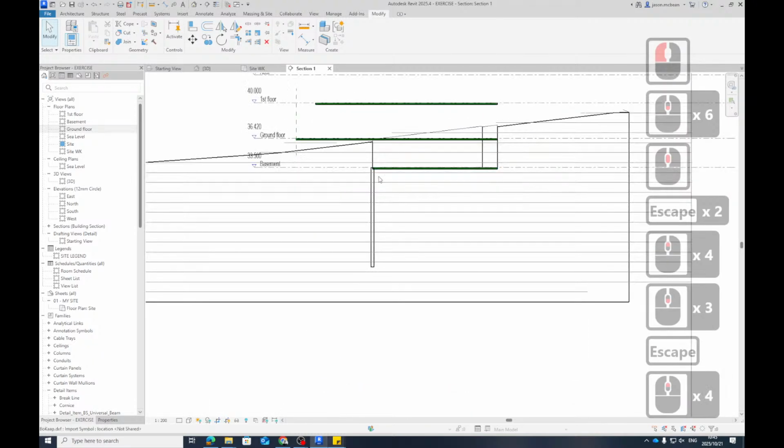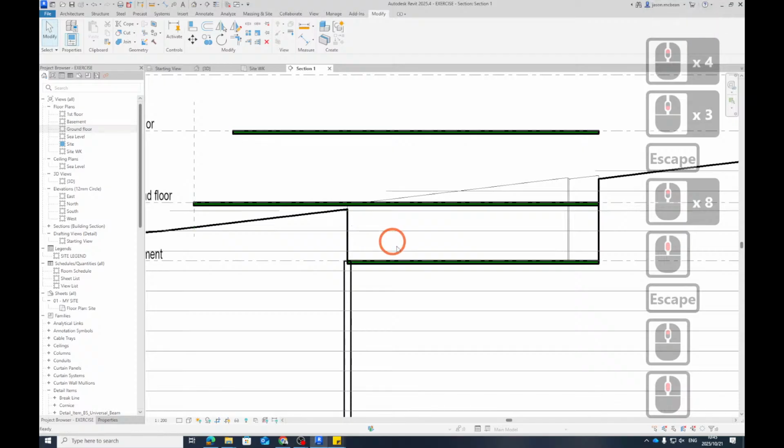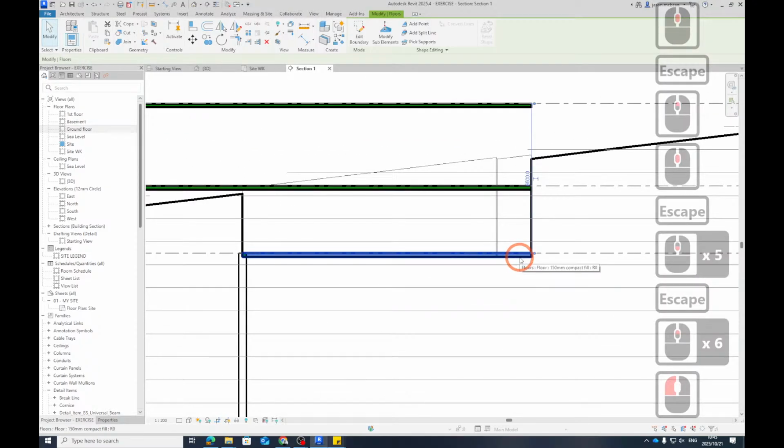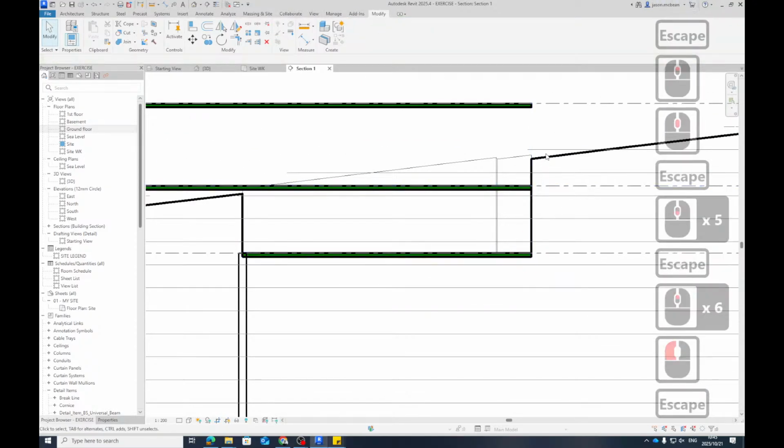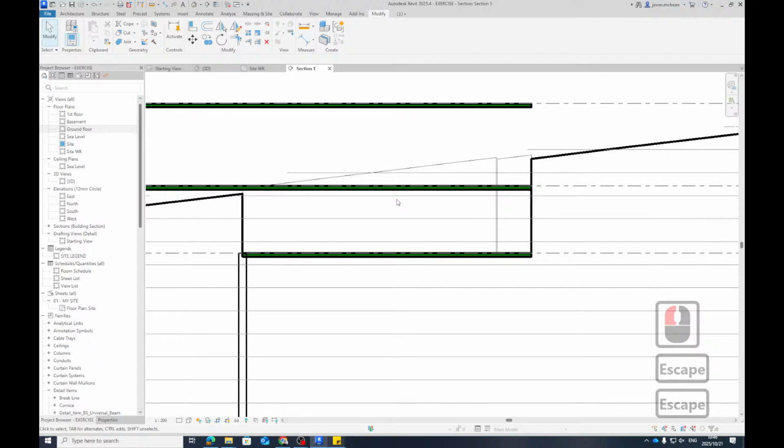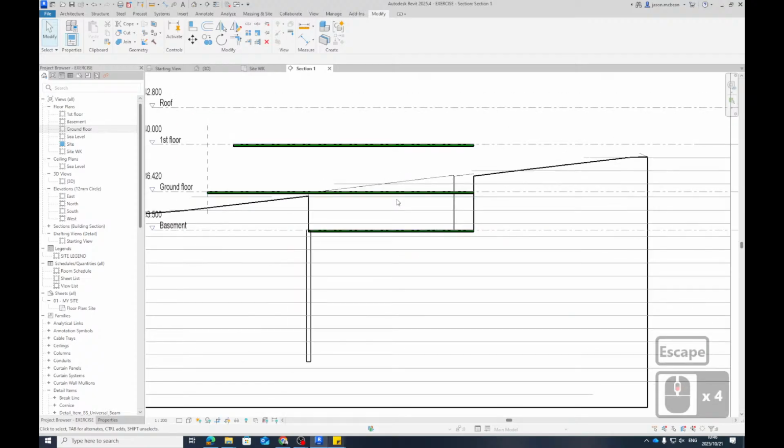Okay. Now, what I try and do, you see these are excavating my topography. I'm going to unexcavate because I add another floor level to this. So think of your floor slab. Beneath your floor slab, if it cuts into the ground, you're always going to have fill. You're going to have a fill layer. I make a new fill layer and I make that my excavating layer, because you'll see it will start interfering with your walls in a minute.